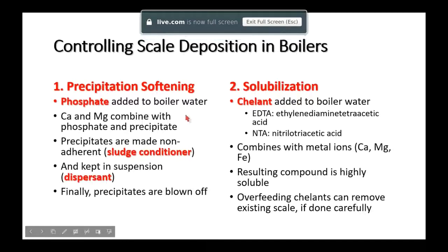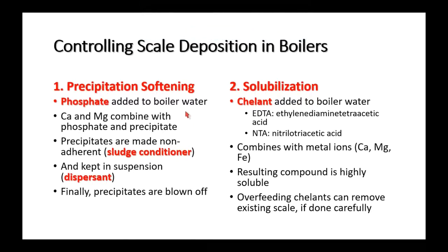We're looking at the different effects of scale and how it basically costs us money and damages metal: under-deposit corrosion and overheating. We introduced terms like top dryness and departure from nucleate boiling, and saw how it affects circulation and all this kind of neat stuff.